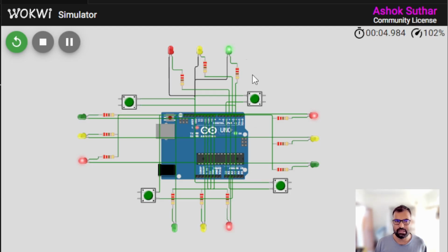Here is the system running under normal operation. Traffic lights transition automatically between lanes based on the program timing sequence. Notice that before switching the next lane into green, the controller briefly enters a complete stop state before activating the next traffic light. When an emergency override is triggered, the system temporarily interrupts the normal cycle and prioritizes the selected traffic route before returning back to standard operation.